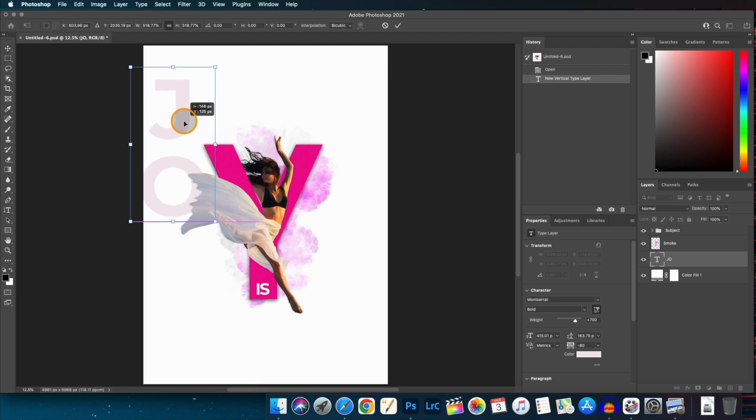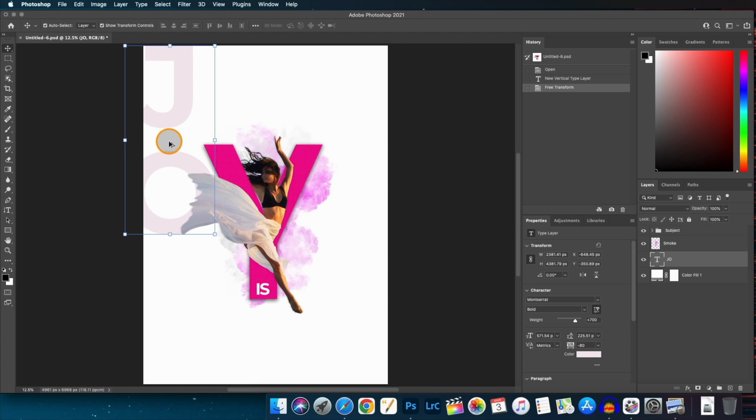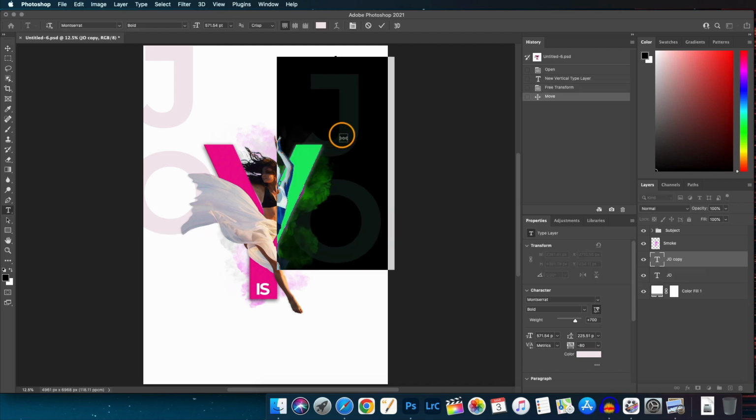You have to select it as we have done earlier also. Let's now duplicate the layer by holding the Alt key. Just before that you have to press OK to confirm it, then hold the Alt key, and when the cursor changes just drag along. You will get another duplicate of the layer. Then edit the layer by double clicking on that.